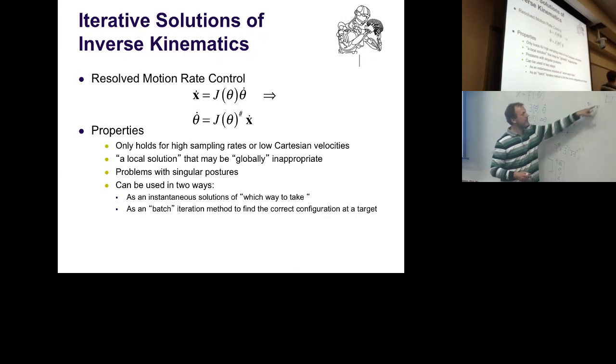In order to move in this direction, you would first have to move in this direction, and then you start to have degrees of freedom which can move in and out. But you can never move beyond this point since it's here fully stretched. But even if you want to move inward, which is your normal workspace, you first have to move out, and then you can go down. Okay, and this is when you get algebraic singularities.